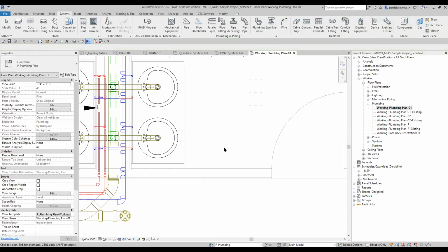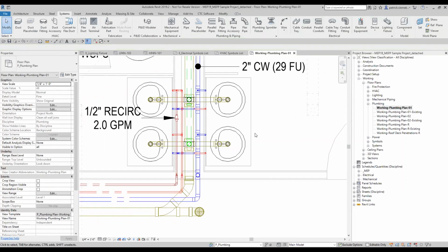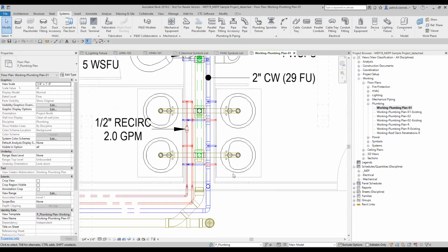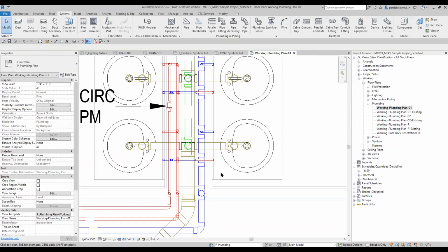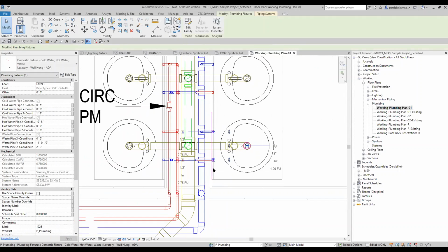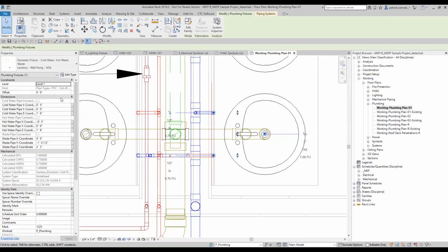A lot of the families on the mechanical side are driven off of a mechanical configurator. What that means is that if I select one of these families and look in the properties, you have control of moving your different connections. It's created based on a Cartesian arm, meaning that I can move any connector in an X, Y, or Z direction.